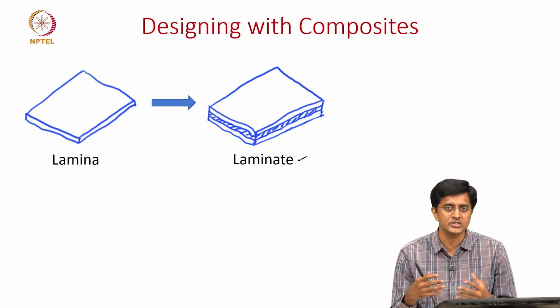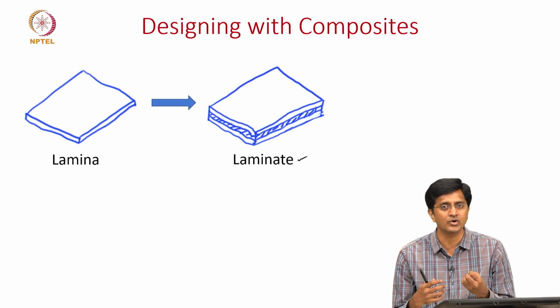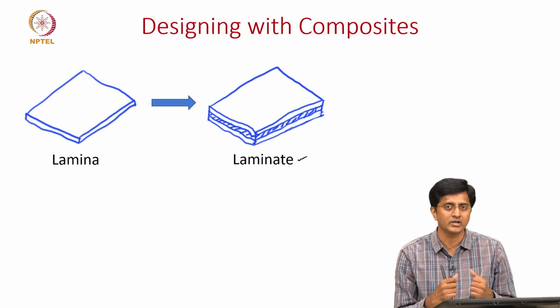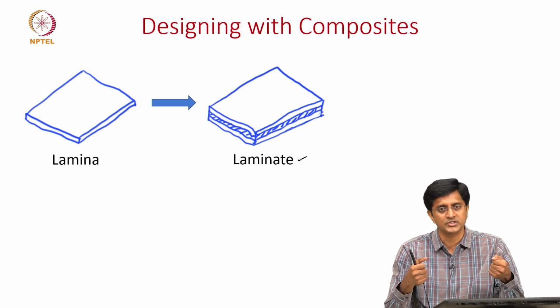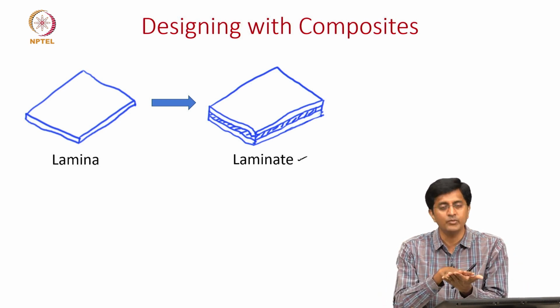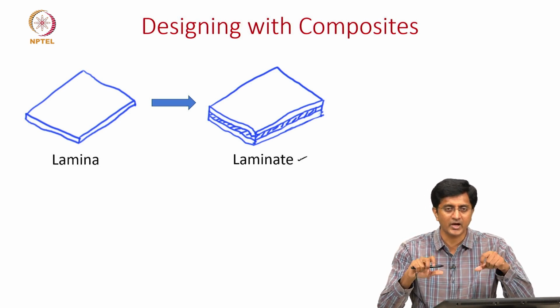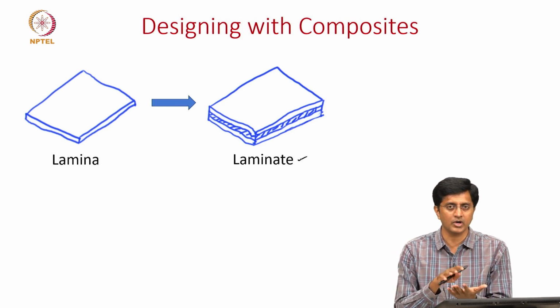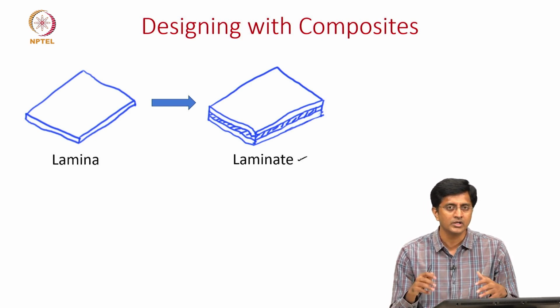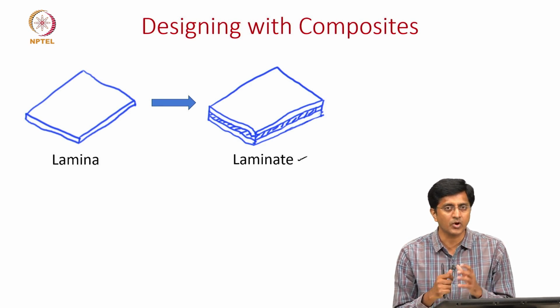This stacking sequence is something a designer has to come up with to meet the particular requirement, because some structures might only have a longitudinal or in-plane load, but other structures might have torsional loads. Depending on whether it is a torsional, in-plane or bending load, the stacking sequences can be optimized for these specific loading scenarios.